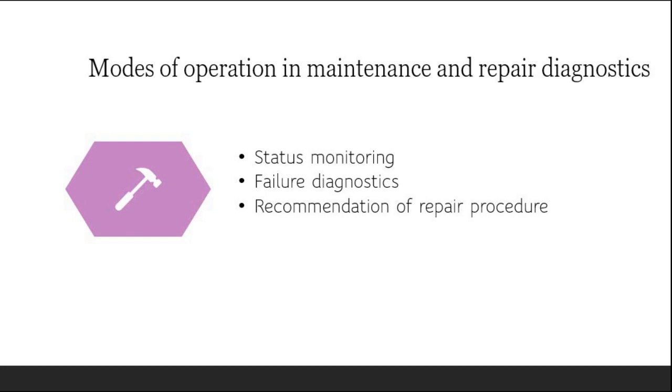The second mode, failure diagnostics, is invoked when a malfunction or failure occurs. The purpose is to interpret the current values of the monitored variables and analyze the recorded values preceding the failure so that the cause of the failure can be identified. In the third mode of operation, the subsystem will recommend to the repair crew the steps that should be taken to effect the repairs.